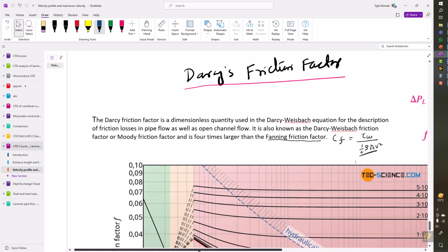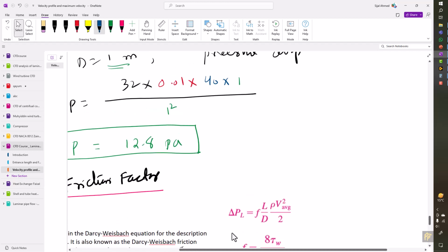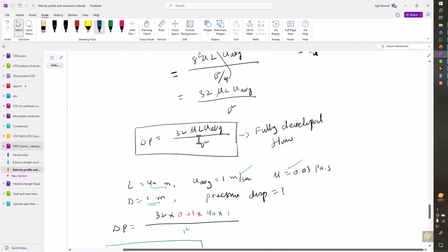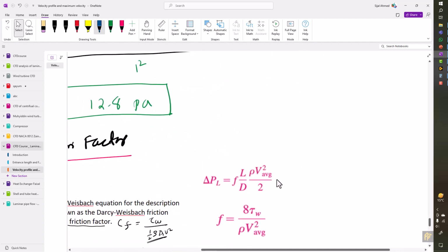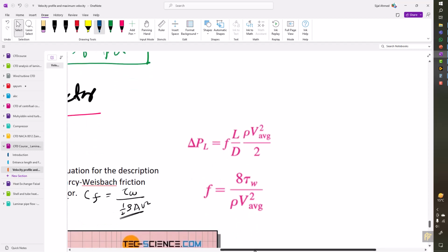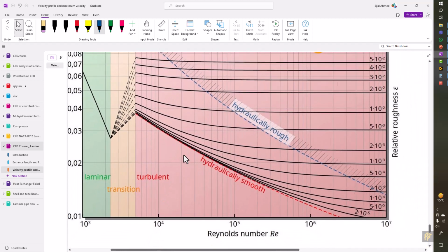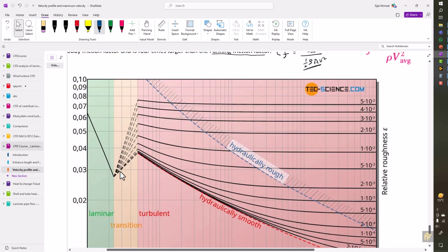And the formula for the pressure drop. So basically we are continuing with the same thing, that is the pressure drop, but we want to cast this formula in a different form, in terms of the friction factor. And why do I want to do this? Because for the friction factor, we have the Moody chart, and in this diagram we have 3 sections. One is for laminar flow and one for the transition flow.